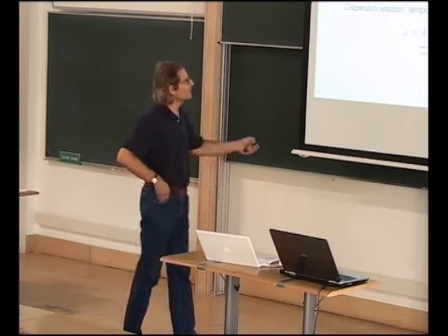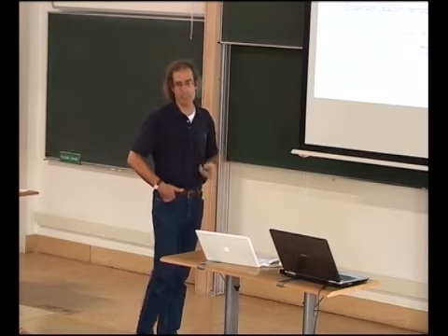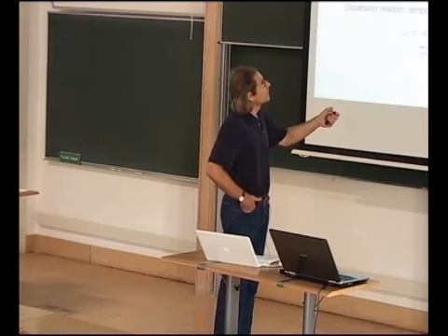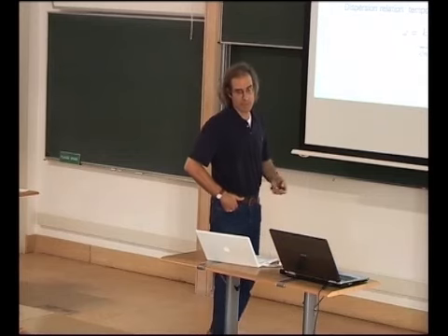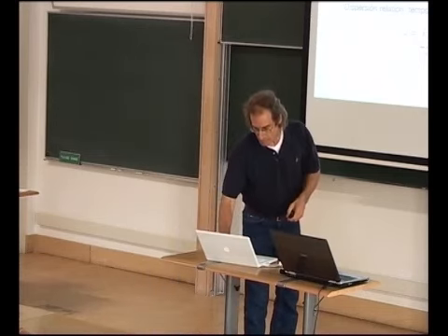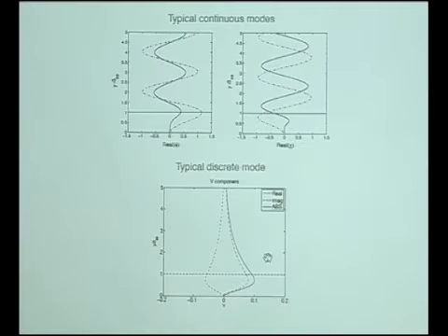Now, those elongated disturbances can be understood in the context of our Sommerfeld theory by noting that the continuous modes are just vortices. In the free stream, it's just vorticity that is convected along, and it just decays by viscosity. It's not an unstable disturbance. However, that's true of horizontal vorticity and vertical vorticity. They both are convected along and decayed, so they have exactly the same dispersion relation, and this becomes a resonant forcing term, and you get linear growth. So the coupling between the free stream disturbance and the boundary layer comes about through that, and it generates the long features.